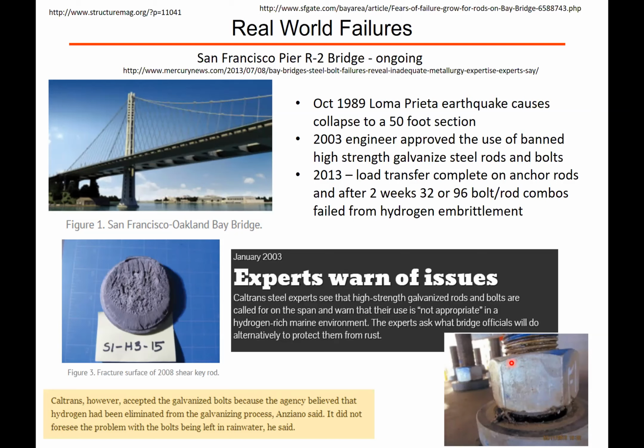And so, when we design a component, of course, we can do testing and modeling in the lab and calculate all the stress concentration and such. But what we really need to do is real life testing, accelerated testing, where we put these materials and these components into conditions that we think they're going to be exposed to, the environmental conditions, and accelerate that to see what's going to happen in X years, and of course check in on them to do all this testing.